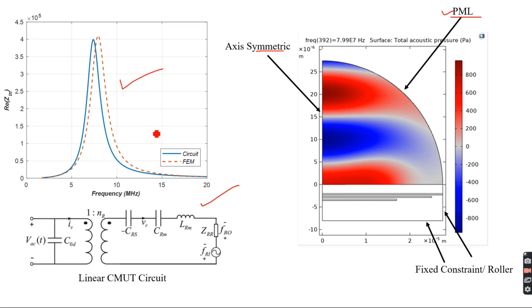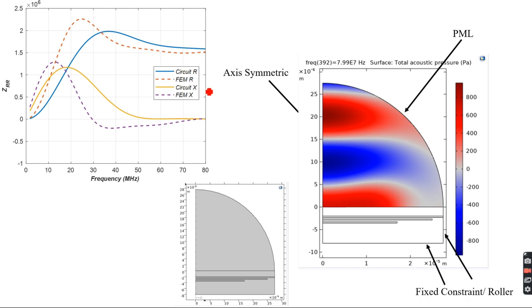The difference that you see is, well, I think this quality factor is much lower, a little less than 4.5. The problem over here is that when you do this numerically, the acoustic port in the circuit, the termination, is in its own radiation resistance, which are Bessel functions of the form, if you remember, 1 minus J1(2x) over x, something like that, where x is ka.